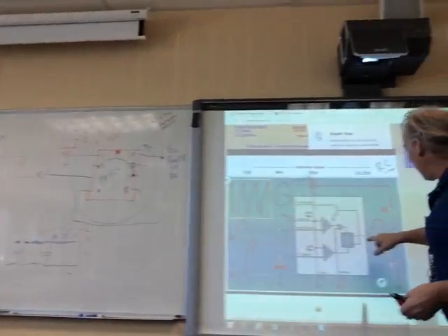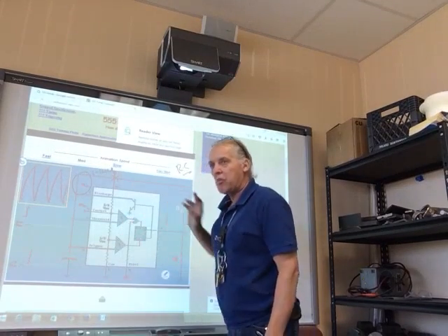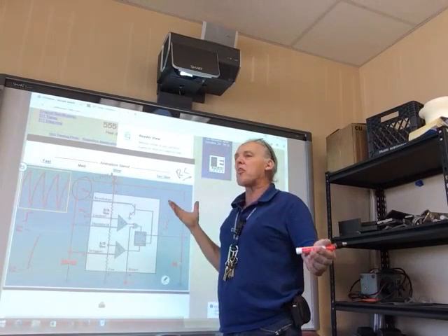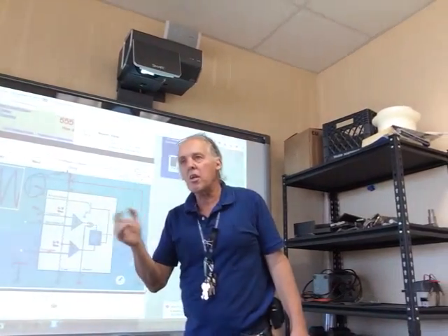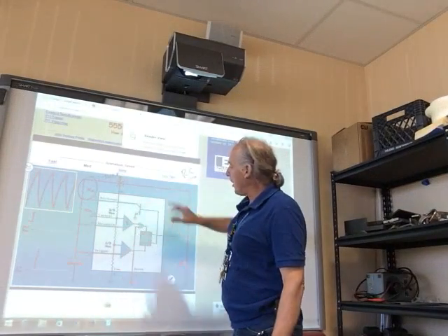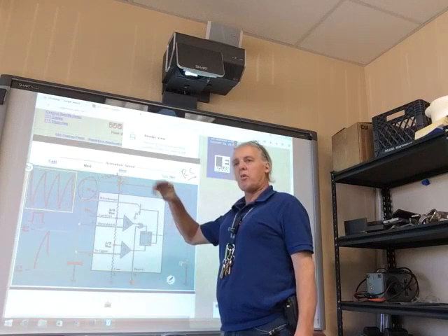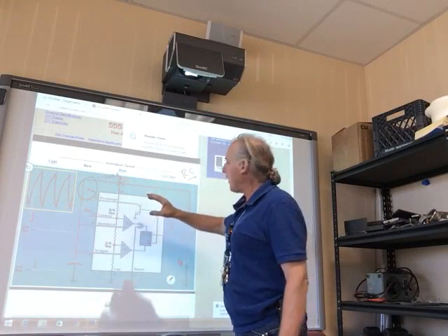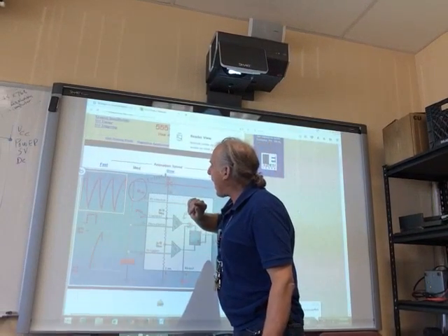So you take a look here. Notice that the base of this transistor, so we're just going to look at that transistor just like a relay, okay? In Bill's class, you've studied relays. It's just like the points on a relay. This output right here closes them, opens them, closes them, opens them. When they close right here to ground, it shorts that out.